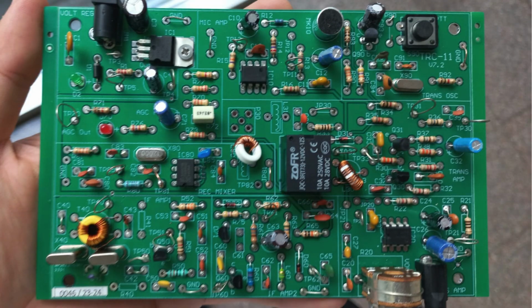TRC11 is the high-frequency radio transceiver, where the word transceiver stands for both transmitter and receiver. TRC11 operates at 27 MHz frequency. It is the radio transceiver which I designed through another course I take this semester at Bilkent, EE-102 Analog Electronics. TRC11 consists of several parts such as different types of amplifiers, voltage regulator, envelope detector, automatic gain control, etc.